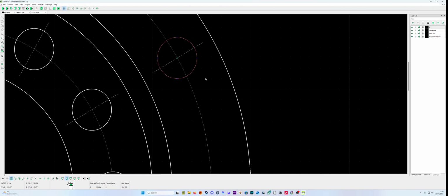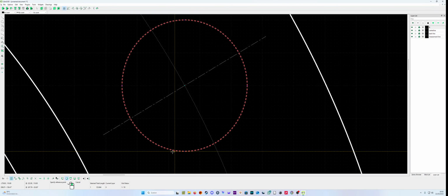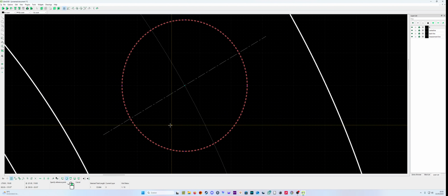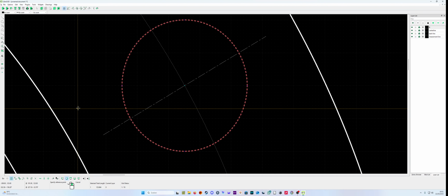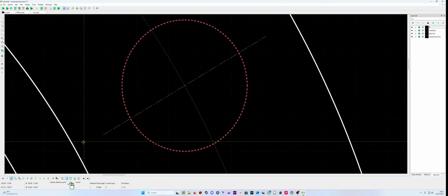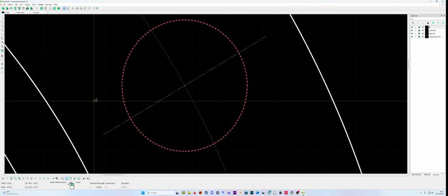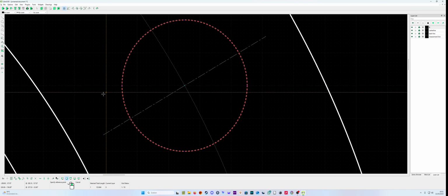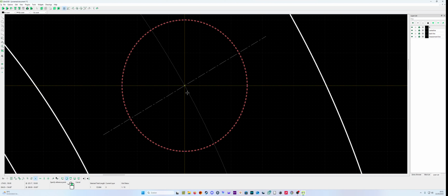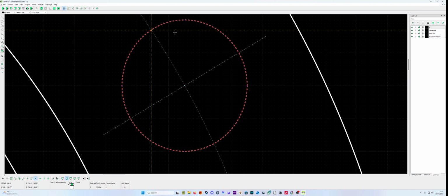Then you say like that, and you say move copy. Select exactly the middle, and now I must explain something. Now you snap on the grid. The grid is this. We call it the grid. You see, snap on grid. So my cross goes from point to point to point, and so on and so on. When I deselect this one, then I can move it freely around. And if I select it now, snap on intersection, then it snaps exactly at where my cross points are. You see that? So that's snap on intersection.